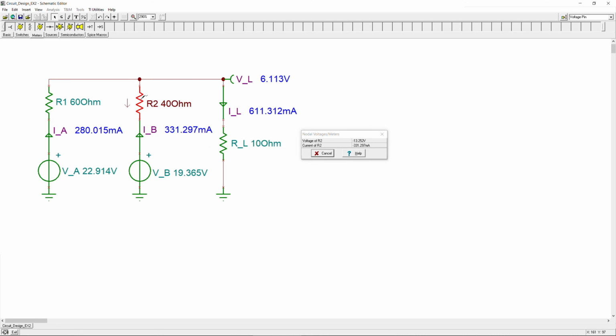You can see the specific voltage and also the specific current for this element. So if I click on this one, you can also see the voltage and the current. But note that the current flows here from top to bottom. That's why it is the minus, so the opposite sign of this current value. It's also shown here. So it is just the choice of the simulator, of course. And again, you see minus 280 milliamps. And we have, of course, a plus because we go from this node to that node.